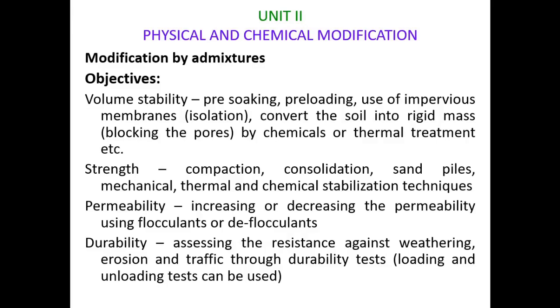There is no proper test procedure to estimate the durability, but repeated loading and unloading tests may help to some extent. Wind-blown dust of unpaved roads or village roads can also be considered as a problem of durability. The temporary methods to suppress the dust include spraying of bituminous sprays, calcium chloride sprays, sodium chloride sprays, etc. The permanent methods are surface sealing, grass cover over the site, etc. Poor chemical durability in cement stabilized soil is due to the presence of sulfates in the soil.